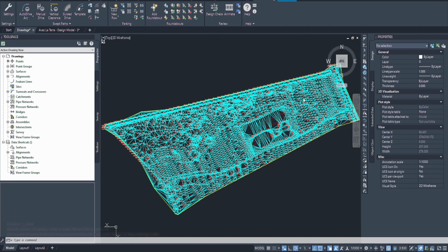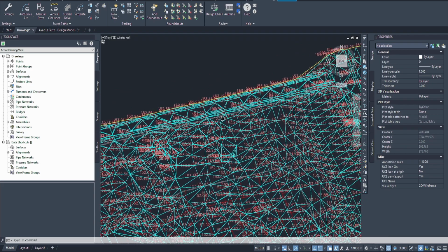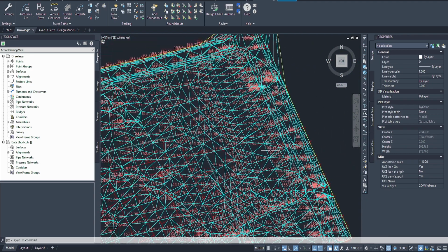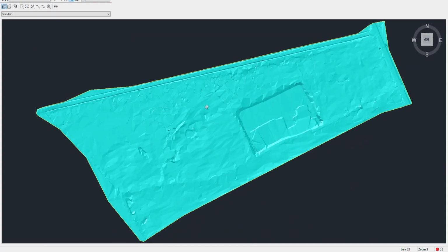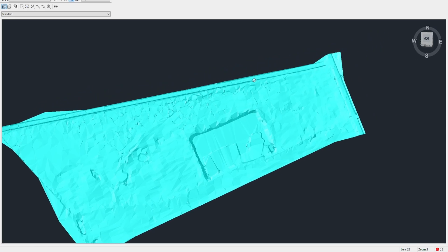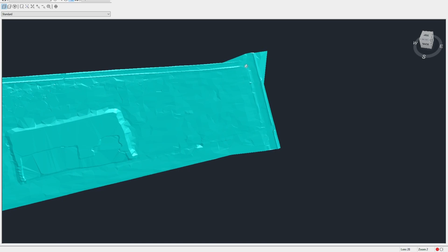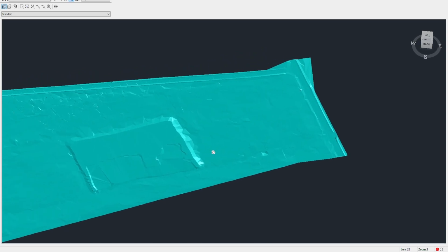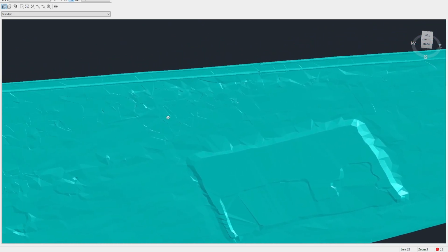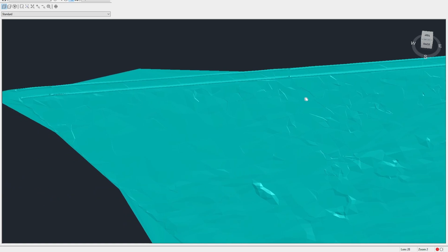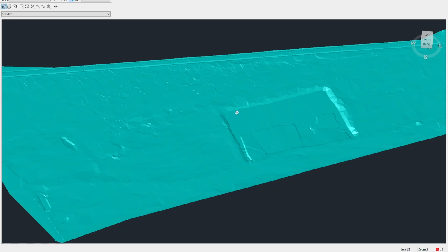Right, so with that you can see I updated this roadway and this one as well, so it looks much cleaner. If I go in object viewer, you can also see the swale is nicely defined, and the roadway as well, and this road as well looks much better. I don't think it is 100%, but it looks much better and we can use it as it is now, and yes, we'll work from there.